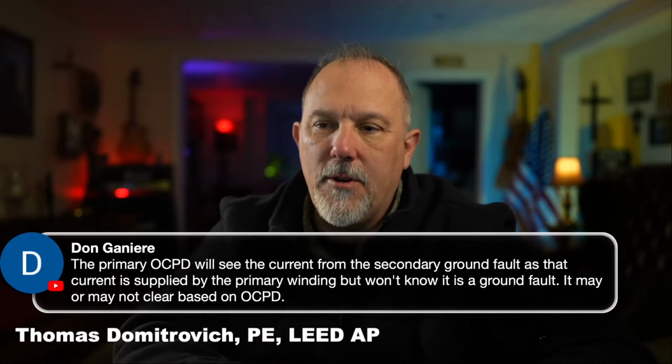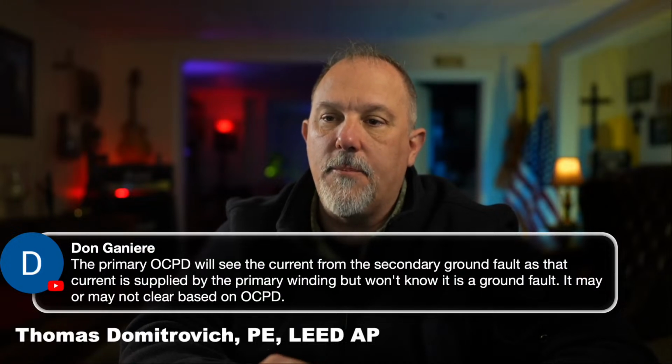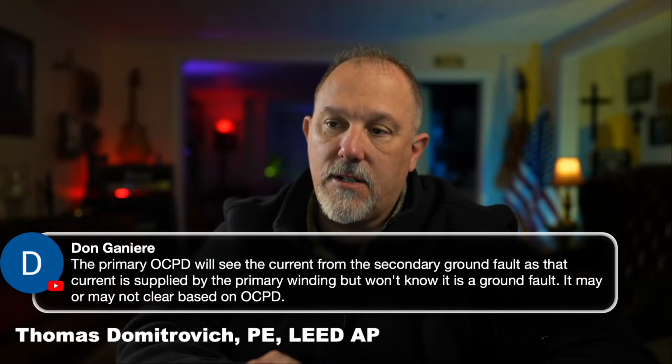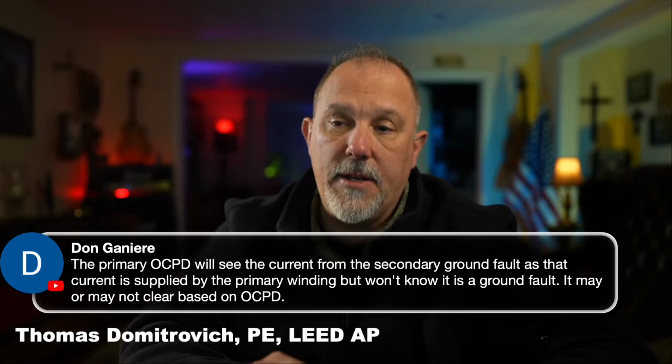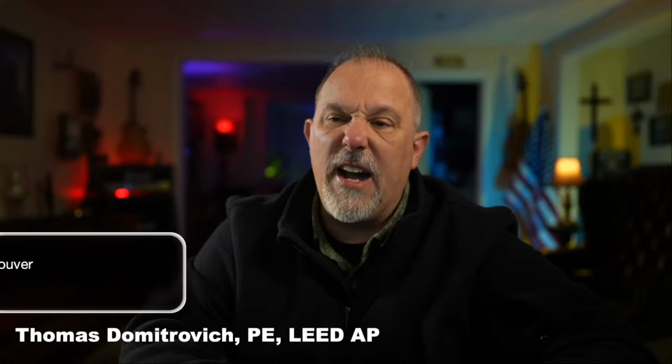So thank you. Don Ganir says the primary OCPD will see the current from the secondary ground fault, as the overcurrent is supplied by the primary winding, but it won't know that it's a ground fault. Yes, because it won't be a zero sequence. It may or may not clear based upon the OCPD. I agree with you. 125%.